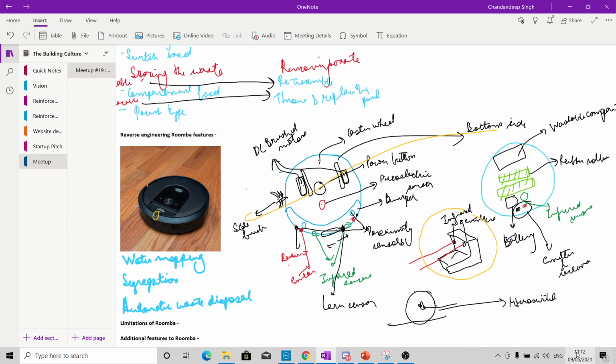I would suggest going for V-SLAM with TurtleBot, because TurtleBot is also based on the Roomba platform. TurtleBot 2 is exactly what is Roomba. Basically it's just having the frame, but then TurtleBot 2 has this Kinect sensor on the top. Then it uses that camera to do the mapping. So there you should start. From there you go to only Roomba specific, because its camera is in some kind of location and it's doing something else. I don't think it's the best way to start with Roomba 980 with how V-SLAM works, because many people don't even know what V-SLAM is.